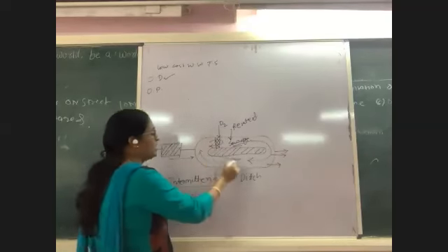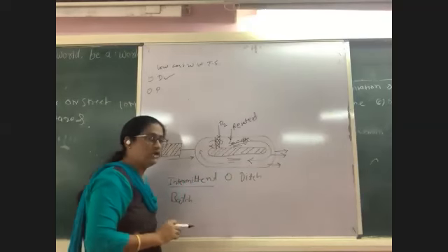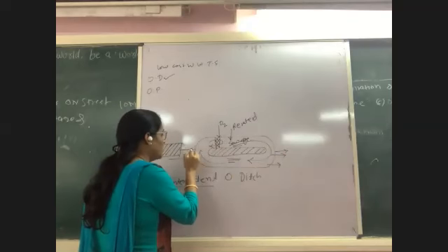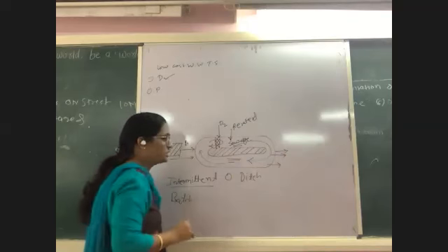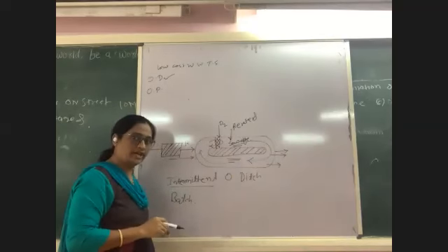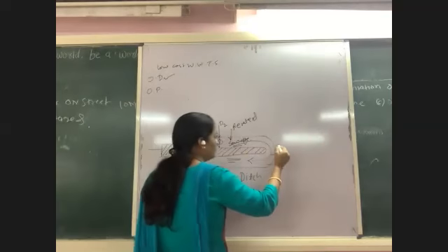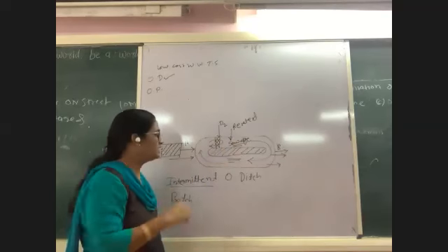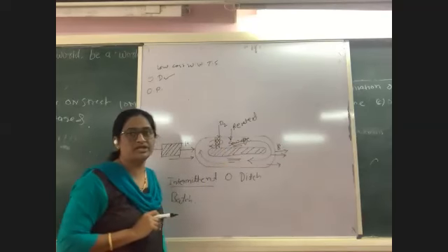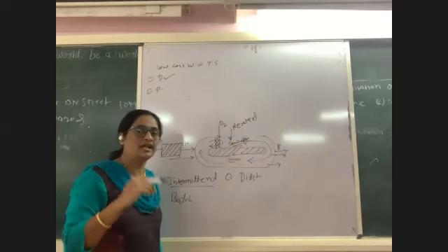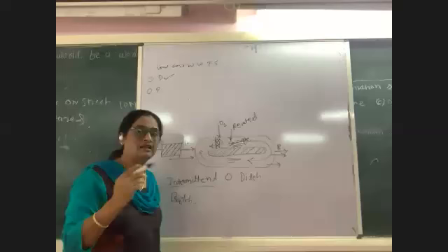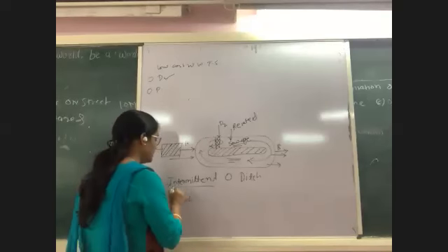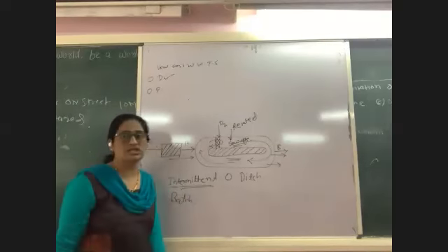Then after removal of the treated effluent and settled sludge, once again you can allow the new batch of wastewater to enter through the inlet valve A and close the outlet valve B. Again, the same cycle will continue. That is, first aeration and then sedimentation and settling of the sludge. This cycle will repeat for another batch. That is nothing but the intermittent type of oxidation ditch.